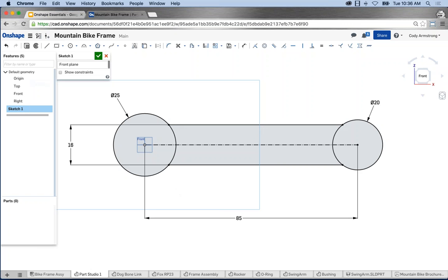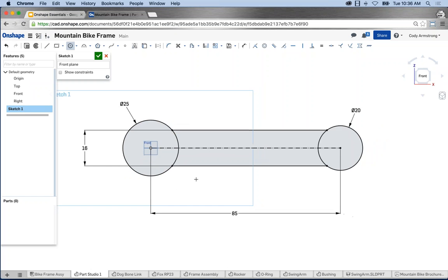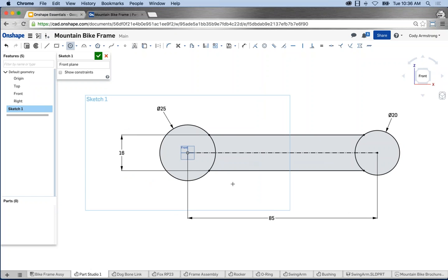Now what I'd like to do is just draw some simple circles. So again, I'll select circle. Now what I'd like is for these circles to be centered inside of our two previous circles. And of course I could come in and left click and do that very easily. I want to deliberately place these circles out of place just to show you how to manually add some constraints. So let's just say you want them to go in here, but you accidentally drew some circles out here. How do I manually get these circles constrained in place?